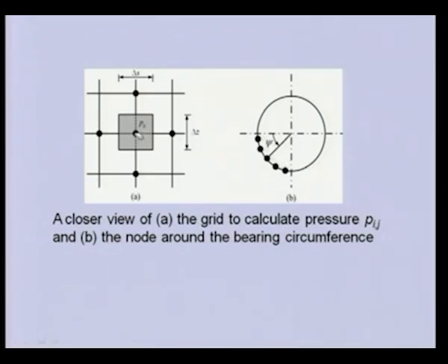But let us see this particular point which is there in the unwrapped position. If you want to see that particular point in the bearing, this is the point. The angular position we are representing by psi. If we multiply this particular pressure by the area, we will get the force it is exerting onto the bearing, because this is the pressure at this point.